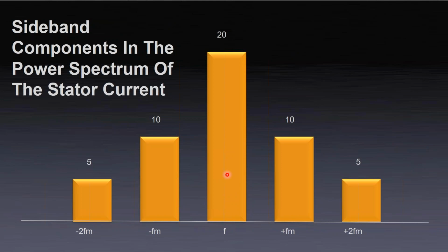Interharmonics are the frequencies to the immediate left and right sides of the fundamental frequency, and they are usually the cause of rotor bar damage when it's due to harmonics. So again, a good power quality analyzer is going to perform an FFT, or fast Fourier transform, analysis to view the current harmonics and identify these high sideband frequencies.